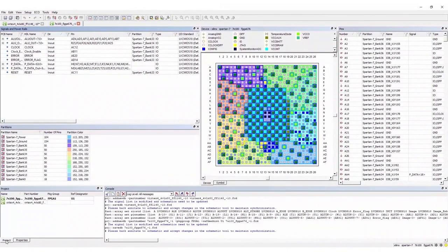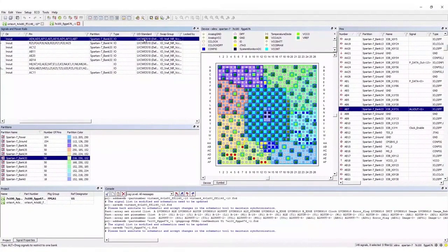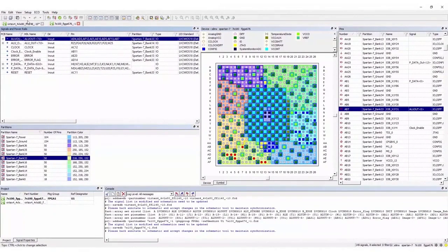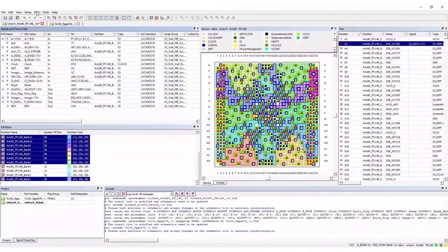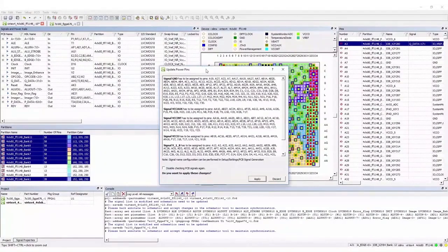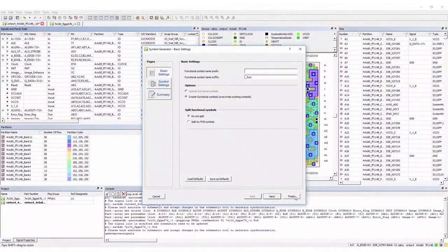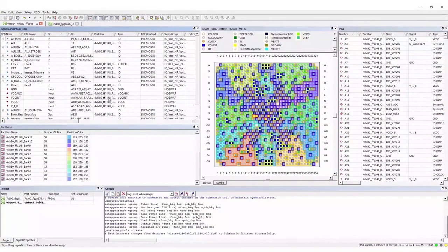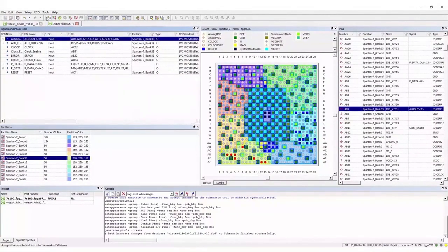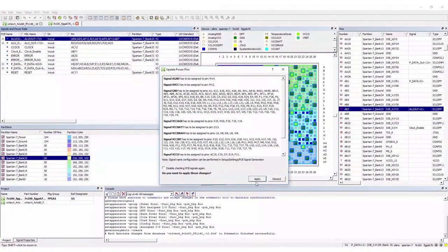For this FPGA too. We can now back annotate the schematic with the newly entered information. This step is particularly interesting as it also connects the power and ground pins automatically according to the user's defined settings. During this phase, you can also optionally generate a functional symbol for your FPGA. We won't do it as the functional symbol already exists in our schematic or is not needed.